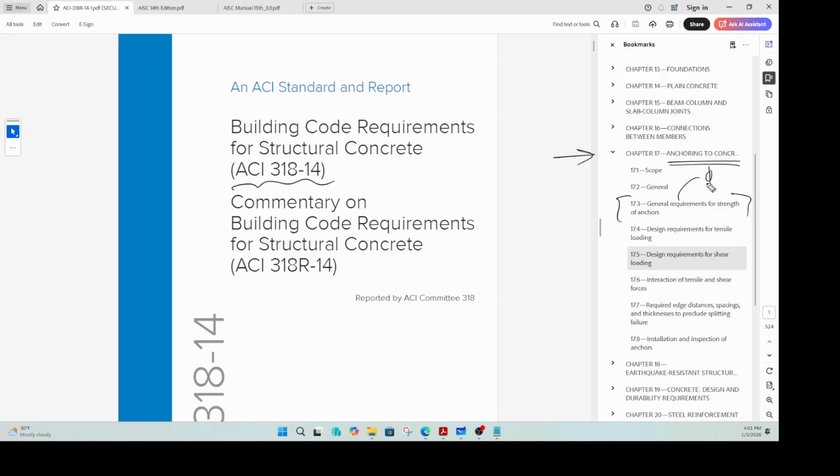Example looks simple, but there's so much visualization that is needed, for example, the shear planes. I mean the weak planes when shear gets transmitted through the anchors and all that, they have to be visualized for you to be in a position to calculate them easily under an exam setting. To calculate these areas, there are few formulae, but then it is better to get a visual of the areas before you can start plugging and checking numbers.